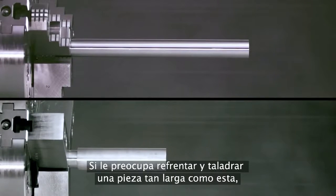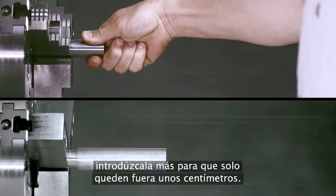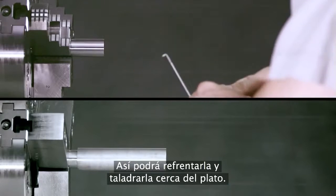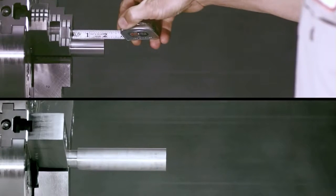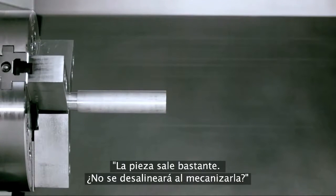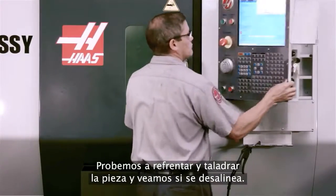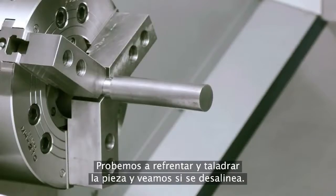If you're concerned about facing and drilling an extremely long part like this, you should choke up so only a few inches are hanging out, and face and drill close to the chuck. You might be thinking, I've got this part sticking out pretty far. Isn't it going to deflect during the cut? Good question. Let's face and center drill our part and see if it does deflect.